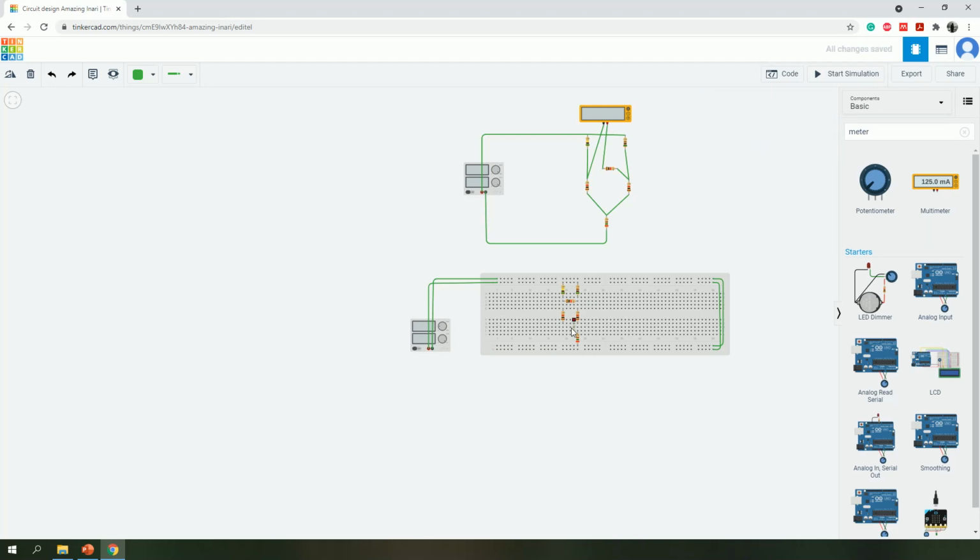And one more thing you will have to do is, again, I have done this connection. Oh, yeah, since I've connected here, these two resistors are connected, but I need a wire to connect this and this actually. So I'm going to run a wire from here to here. So now this is connected. So all these three, let's go node by node. So this node, that is this node actually.